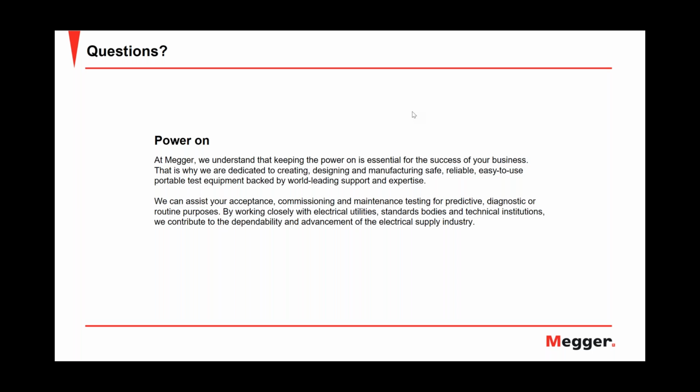So pretty much all the fault location equipment has a DC source in there, which you could call a cap charger. It's a source to charge the cap, but it's also used as a DC high pot function. And this test, as Javier explained, is carried out as a ramp test. So it's nothing prolonged, first of all. It takes like 10 seconds.